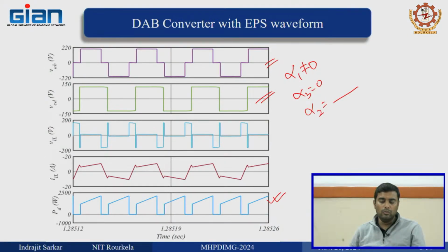So, let us say you have a DC-DC converter, a boost converter, and after that you have a solar inverter. That solar inverter is feeding power to the grid, and when it is connected to the grid, it is in current control mode. When it is in islanded mode, you have to give some voltage reference and frequency reference in order to work in standalone mode.